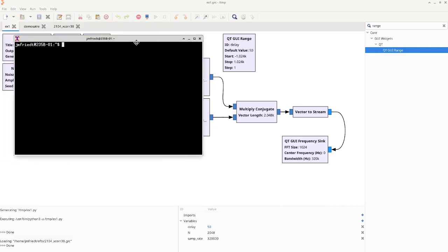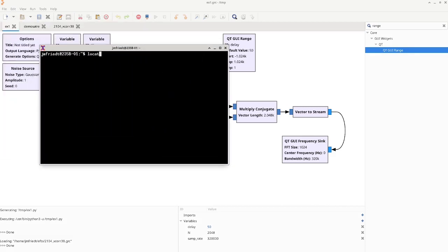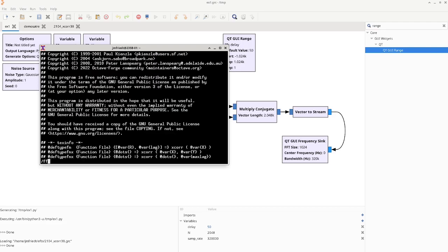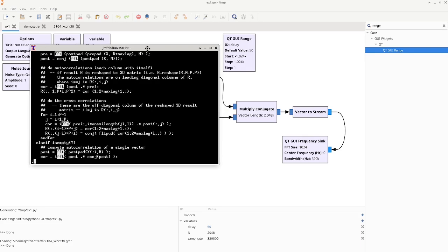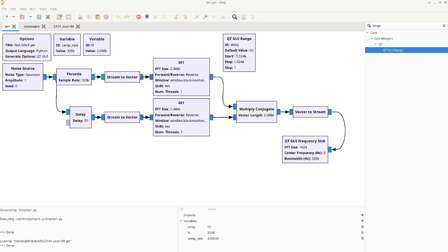This is a very important topic if we look at the implementation of a cross correlation under GNU Octave. We shall see that its implementation heavily involves fast Fourier transforms. Indeed, when searching for FFT in the source code, we do see that the reference signal is FFT'd, the surveillance signal is the complex conjugate of the FFT, and the cross correlation is actually computed as the inverse Fourier transform of the product of these two quantities. So understanding the practical implementation requires that this Fourier expression is understood for a cross correlation implementation.